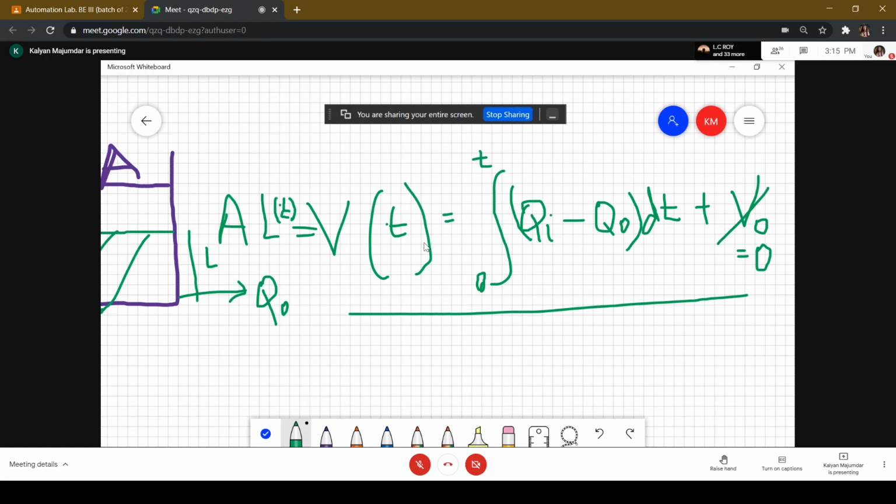What does that mean? You have to take a pump with a larger capacity. A larger capacity pump means you have to take a larger motor, so maybe 1 horsepower to 1.5 horsepower, you have to install a motor and pump there, so that Qi is larger and it can fill up a larger tank in a reasonable amount of time, so 30 minutes, 40 minutes or whatever.